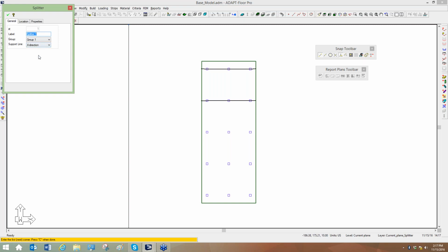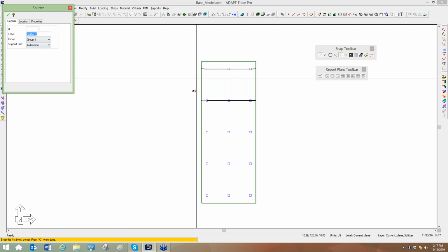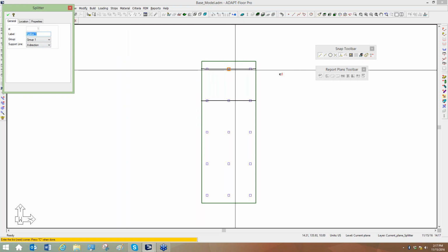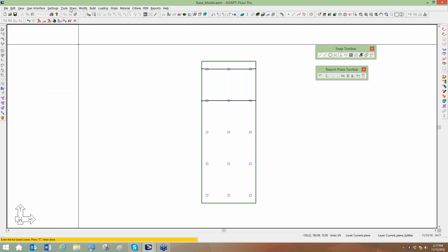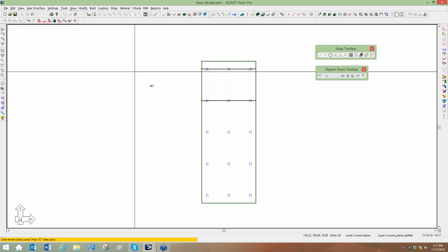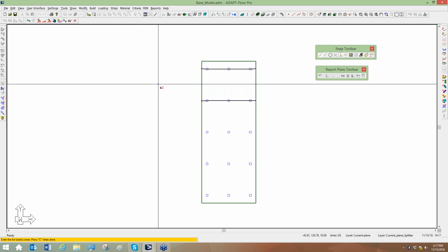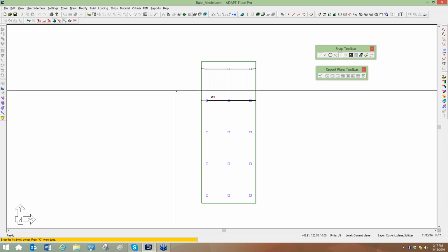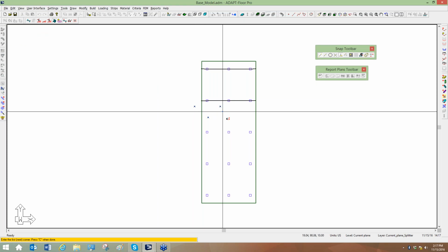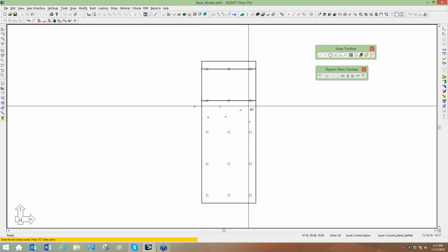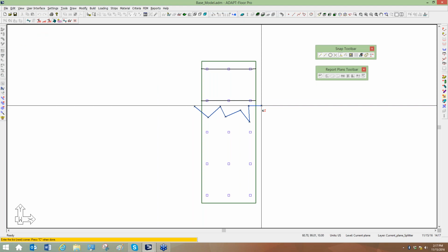So I'll give you an example. We have an X direction input. Remember, we have X direction support lines. These are labeled X, so we need to assign X direction splitters that will influence the creation of tributaries relative to the X direction support line. So now I'll just put a splitter, and again I can make this really any shape. I'll even go up like that and cut across.